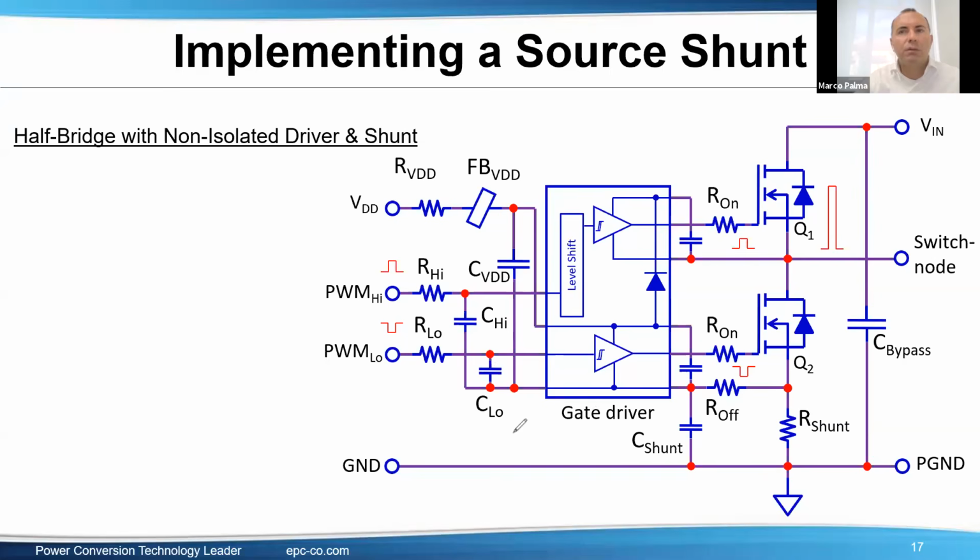Okay. Second question on slide 17, how to filter the PWM signals when the gate driver isn't differential ended? Yeah, that's what we're doing here. That's usually the main problem. If you have a shunt, then the current in the shunt usually comes with some inductance associated with it. So when current is changing here, then you have a peak here. You can try to filter a little bit, but this is going to be a bounce here.